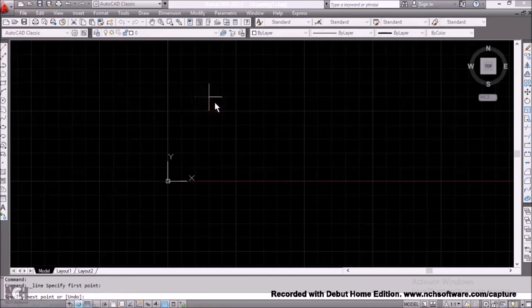I want to make you understand something. This version of AutoCAD, the default interval it gives is 0.5 inches. So that means at every 0.5 inches it will snap. You drop, snap down 0.5 inches for both the vertical and the horizontal intervals. You drop, snap again 0.5 inches, snap down 0.5 inches.